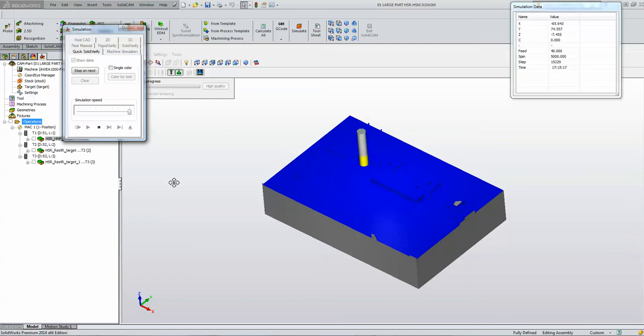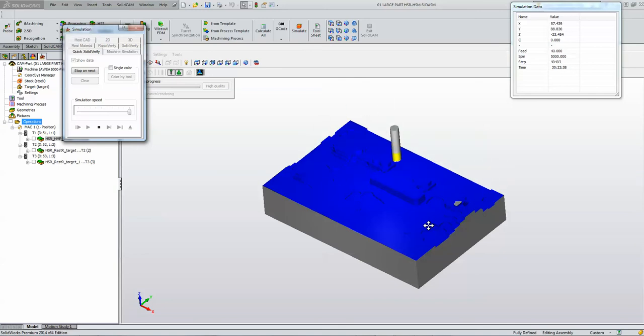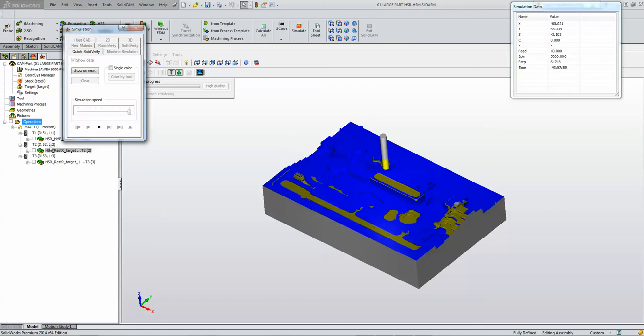Now, if I were to use this simulation in your regular 2D operations, you would barely see any kind of simulation. One, it will jump, the steps in between are too far apart, and you won't see any simulation in itself. Also, in between the operations, it does a little bit of an update, and therefore, when you have different 2.5D operations, which are really, really quick, it'll actually stop in between each one, updating itself all the time. So this is specifically meant for 3D operations as shown over here.